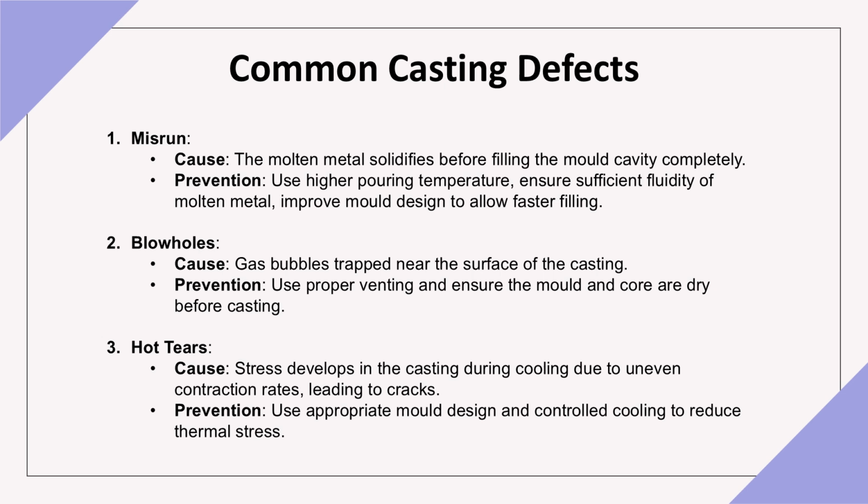Blowholes. These are gas bubbles trapped near the surface of the casting, often caused by poor venting or insufficient drying of the mold. Prevention involves proper venting and drying of the mold and core.